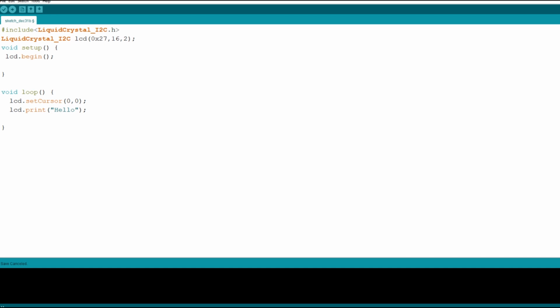So that's why we call our delay function. So let's write here delay and open and close parentheses and put a semicolon and move inside of our parentheses. Let's define 1000 inside of our parentheses, and also we will learn a new function here, and also we can say method too. So our new function is clear.